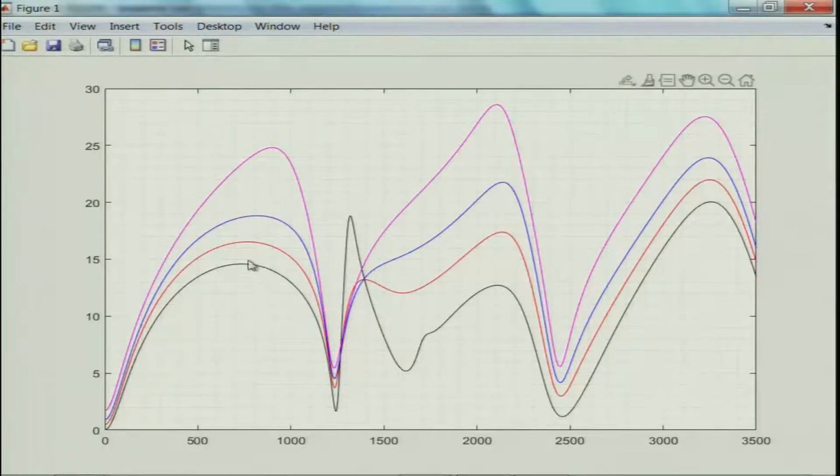What we however notice is that mean flow definitely tends to increase these domes, at least for the cross flow expansion chambers, and black one was for zero flow. So, with non-zero flow these peaks tend to come down, but then these troughs, which are more notorious, more problematic, they are significantly lifted.